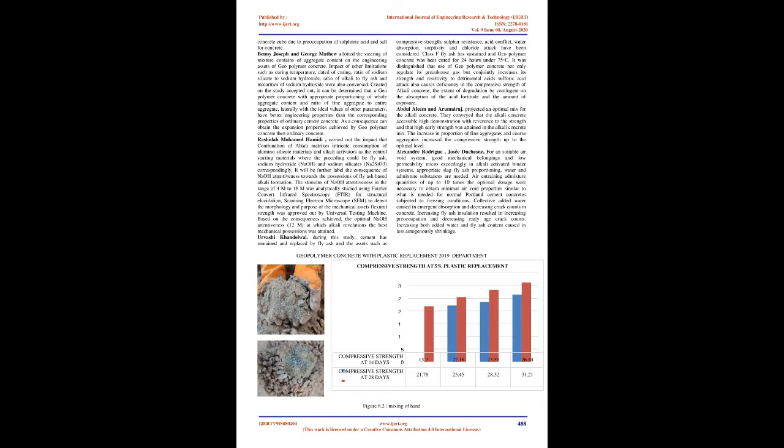Different parameters were used, such as alkaline liquid to fly ash ratio of 0.40, 0.45 and 0.50, ratio of NaOH to Na2SiO3 of 2.0 and 2.5, molarities of NaOH of 10 M, 12 M, 14 M, and 16 M, and check the compressive strength.